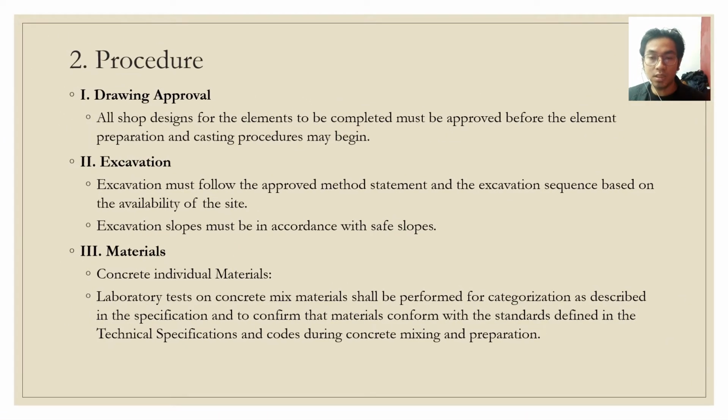Next is the procedure. First is the drawing approval. All shop drawings for the elements to be completed must be approved before the element preparation and casting procedure may begin. Second is the excavation. Excavation must follow the approved method statement and the excavation sequence based on the availability of the site. And next, the excavation slope must be in accordance with safe slopes.